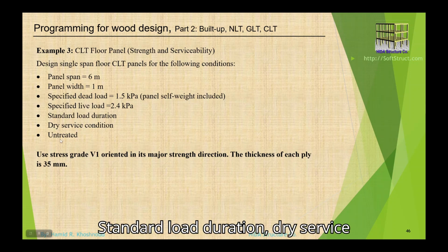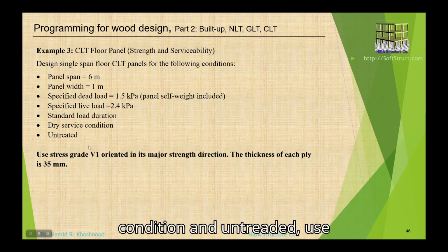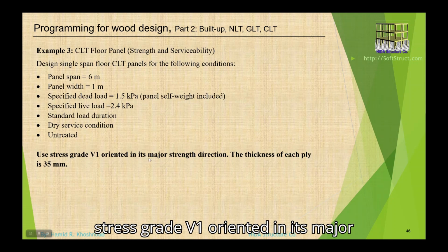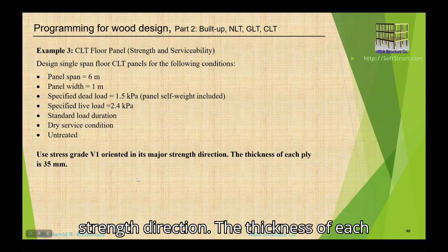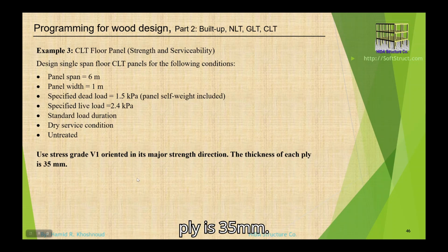A standard load duration, dry service condition, and untreated. Use stress grade V1 oriented in its major strength direction. The thickness of each ply is 35 millimeters.